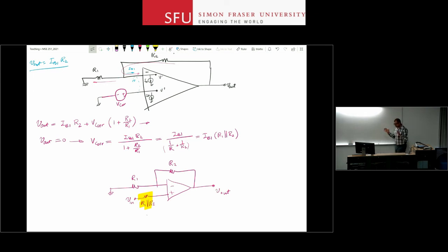Now, all that said, if I_B bias is a consideration, if I_B bias is annoying you for whatever reason, my best solution, my first suggestion to you, is to use a different op-amp. You can get op-amps nowadays. If it is a CMOS op-amp, the input bias current is on the order of sub-nanoamp. Picoamps is typical. And if you really, really are interested, you can find op-amps that have femtoamps of input bias current, which in most cases is really zero. It's not going to affect most circuits.